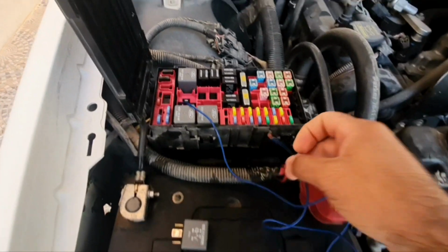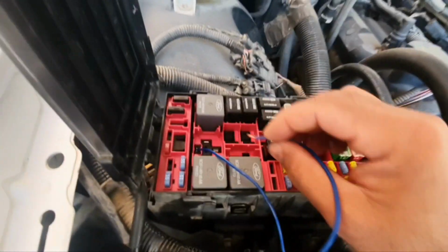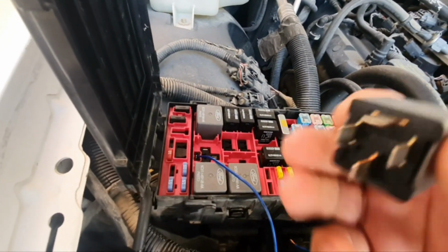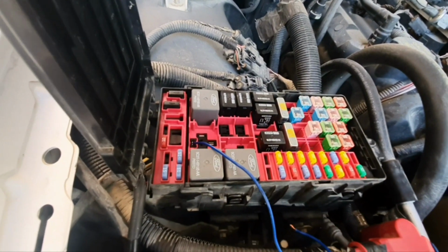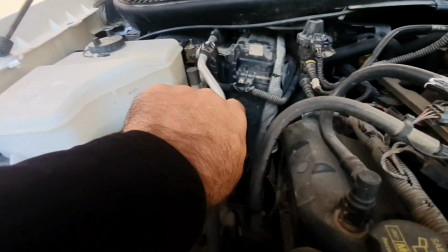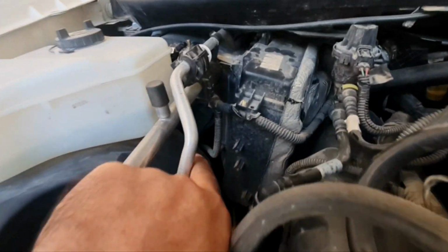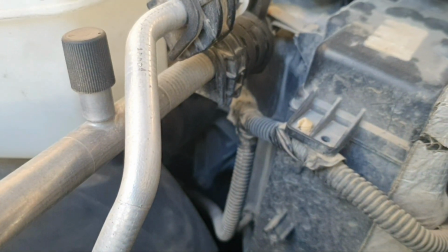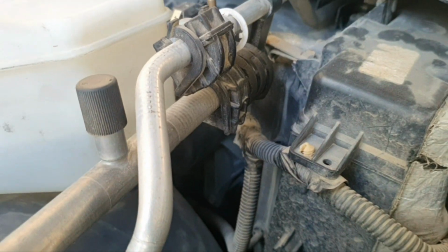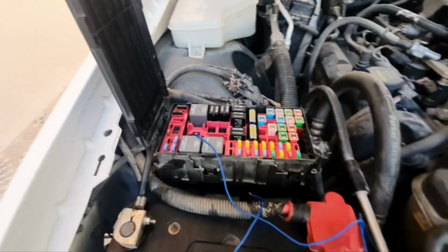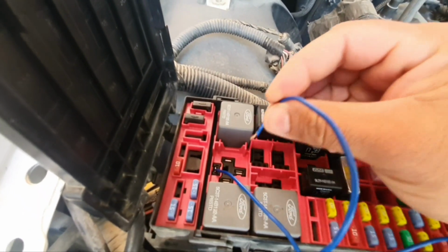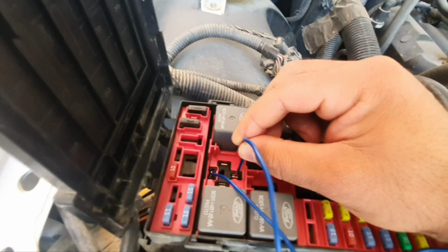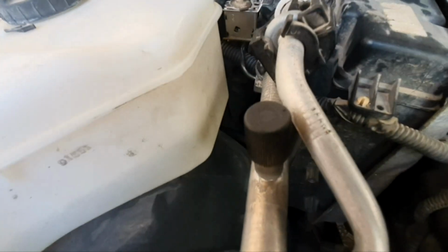Okay, so now I put this wire, and I said that I will put it at terminals 30 and 87. And also the blower fan is located down there. I don't know if you can see it, but it is inside there. Okay, so we can hear it from here. So let's try and put a jumper wire here and see if that blower starts blowing. And it does start.